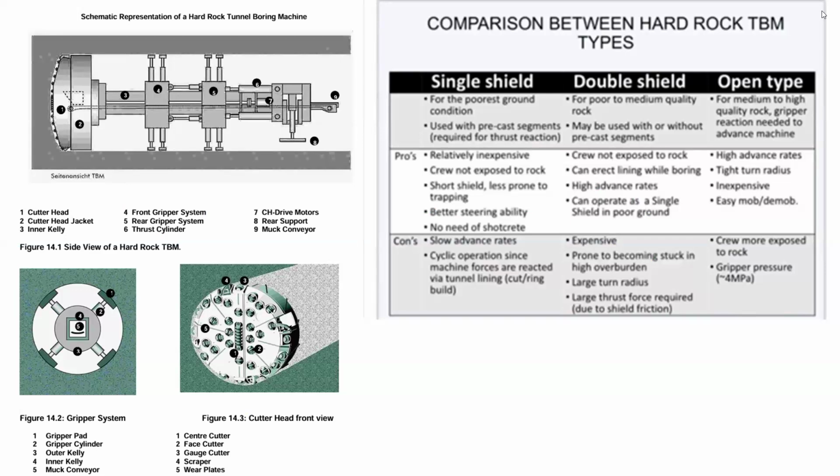It's not just like a soil TBM, because in the soil TBM we have seen that it is applying face pressure, it is circulating some slurry, some air pressure, sometimes bentonite slurry, and also it is taking the thrust from the installed segments. The rock TBM works basically on the thrust taken from the rock surface. So whatever the ground it is excavating, it is taking the thrust from the excavated rock. That is how it is taking the thrust. It is called gripper. So you can see here.